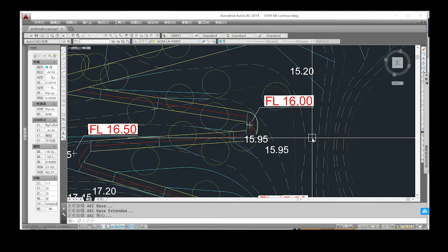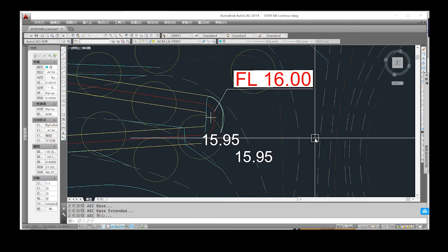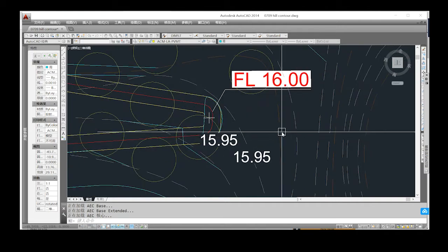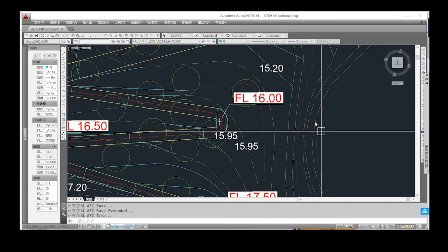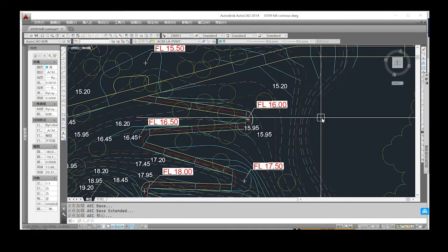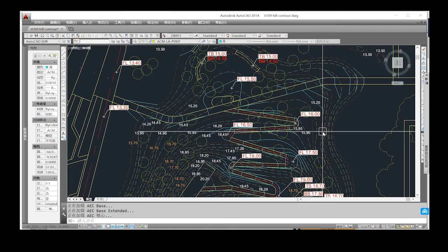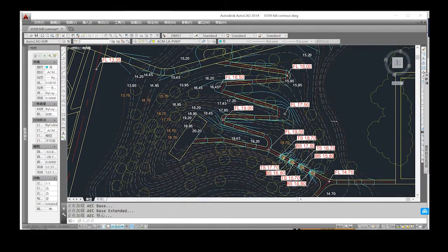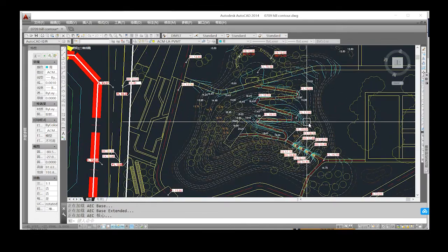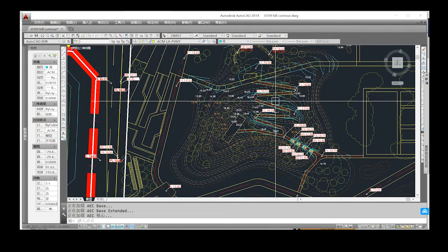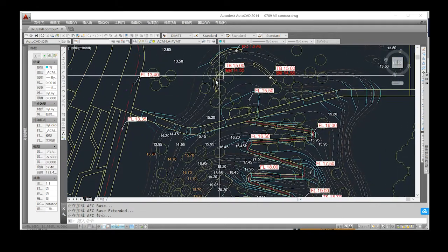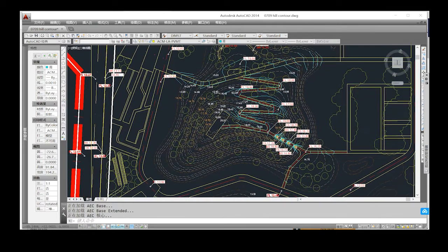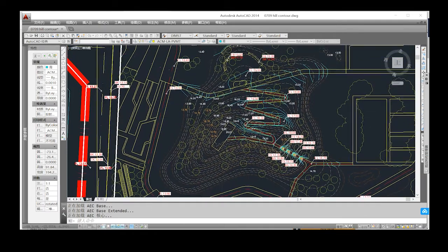And for the contours, I just want to bring up two major points that are important. The first one is contour breaks. For the most part, contours don't break because they are imaginary continuous lines people created. So they don't exist physically, but they do break when they hit structures with a certain height and elevation, and that's where they will break if you draw them in plan.